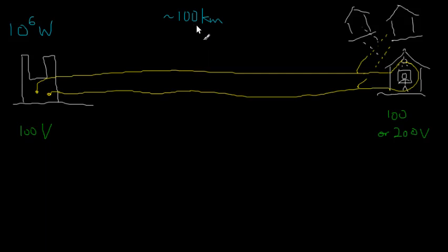we have this distance. Now we need the resistance. We need the resistance in order to calculate how much power is lost in the cable. To get an idea of what the resistance value is, we can use the resistivity equation.